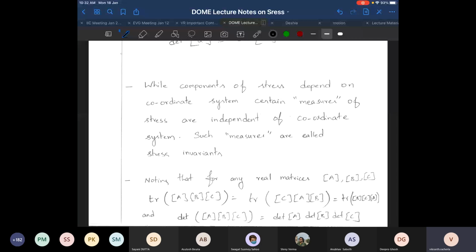What is wrong with this statement? In uniaxial tension, when the material was loaded along the x1 direction, the condition for plastic yielding was when sigma 11 exceeds the yield strength. But I cannot use this as a generalized yielding criterion. What is the problem with this statement?